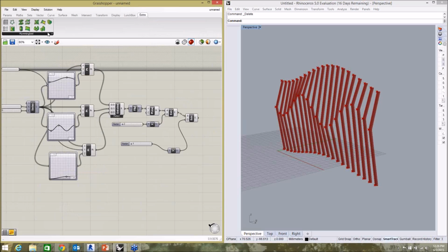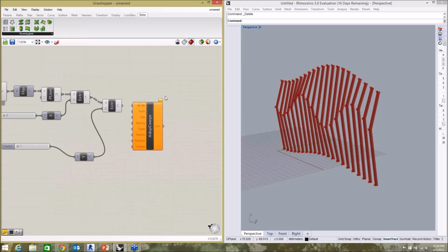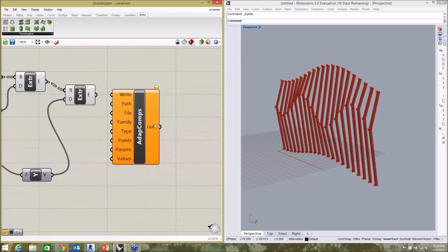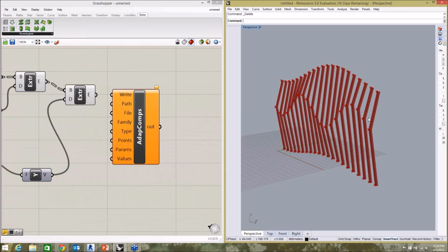And what I'm going to do is it's going to allow you to pick from different objects that you're used to in Revit. So whether it's beams or floors, and we're going to show some of these here in just a little bit. So what I want to do is I actually want to use the adaptive component for this. And I'll show you why in just a second. All right, so this is going to be an adaptive component in Revit. And basically it's going to be a 1, 2, 3 click.